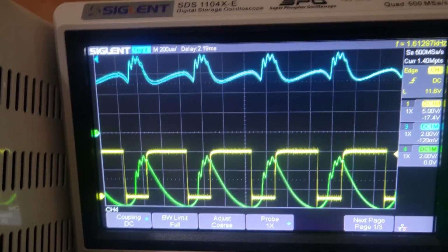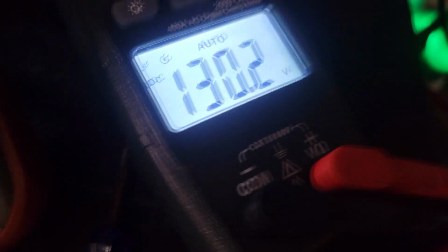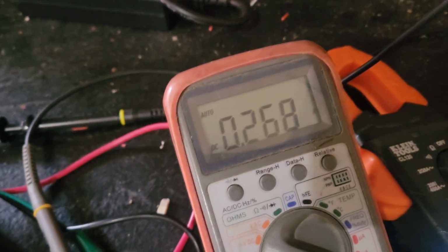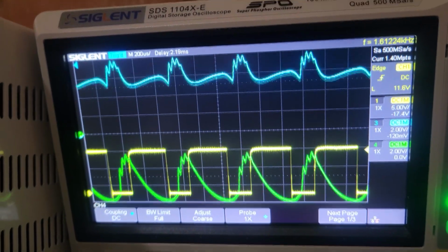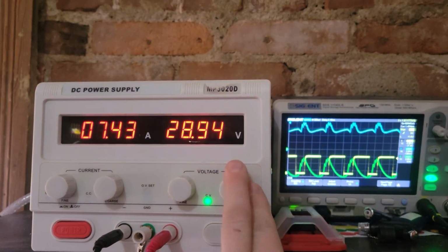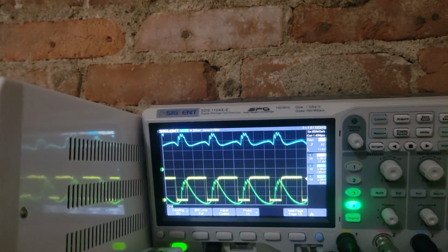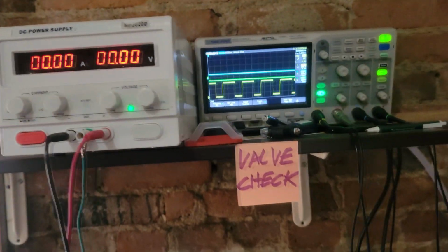Look at that waveform. We're at 134 volts starting out. Definitely appropriate production for the voltage level of 130. Still less than 300 milliamps across the cell, but that waveform is a nice waveform, equal opposite polarity pulses. We're consuming 7 amps though, but it's wild that just those inductors are causing all that.